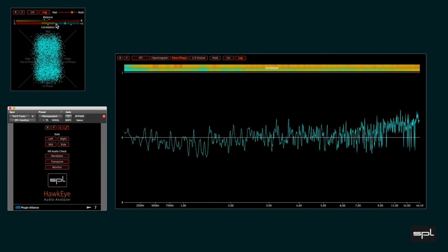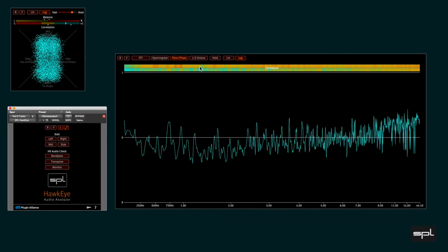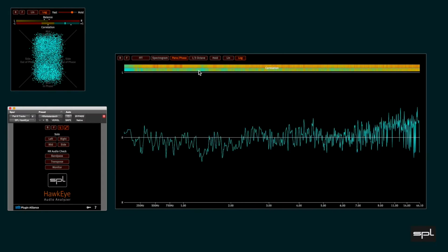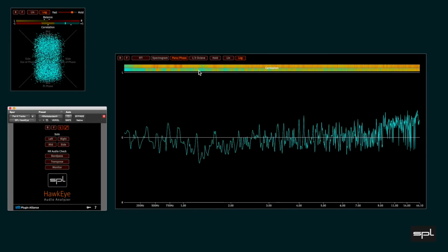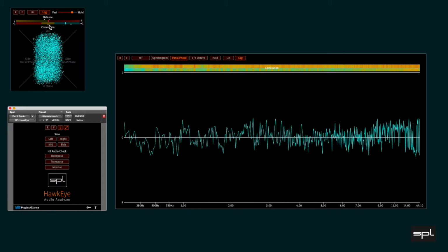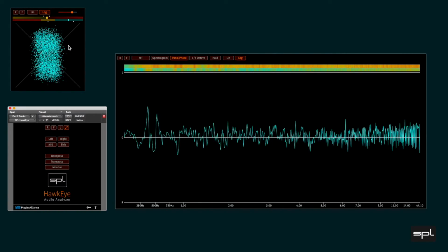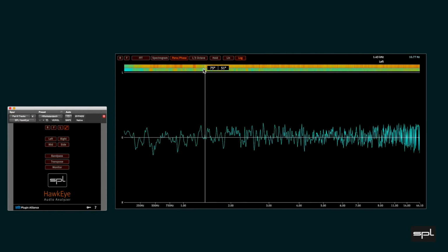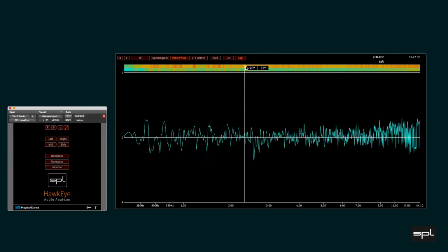Furthermore, there are two correlation stripes that show phase relationship of 4096 individual frequencies by applying a similar color coding as used in the correlation meter. Again, these bars complement the correlation meter of the vector scope. The lower correlation stripe shows the momentary correlation of each frequency, whereas the upper correlation stripe holds the negative correlation value over the time of measurement.